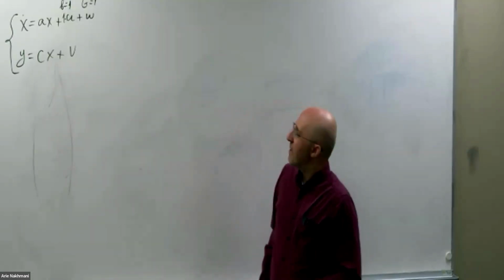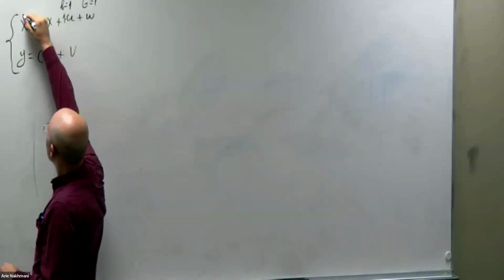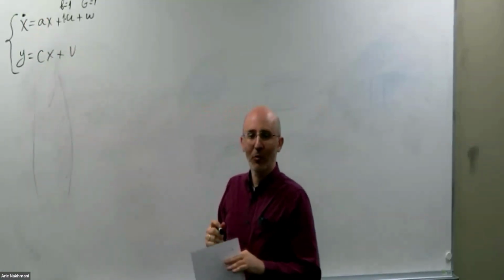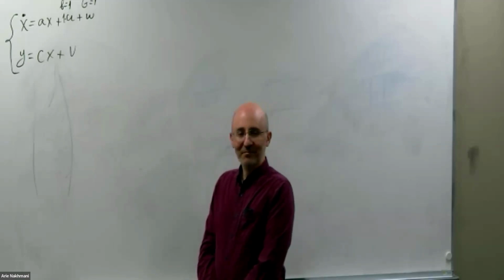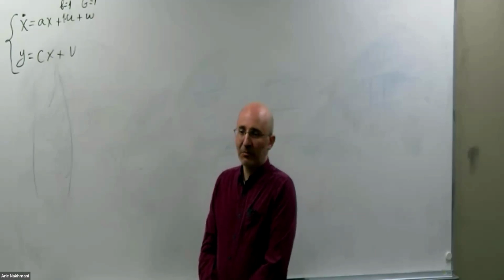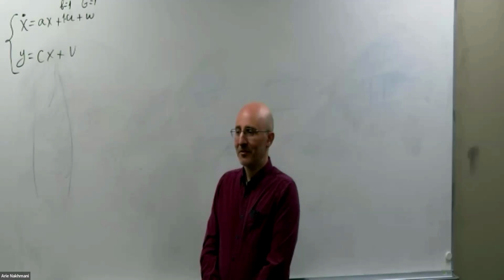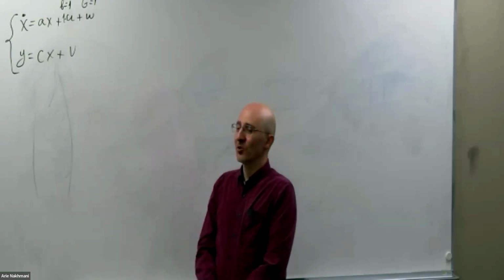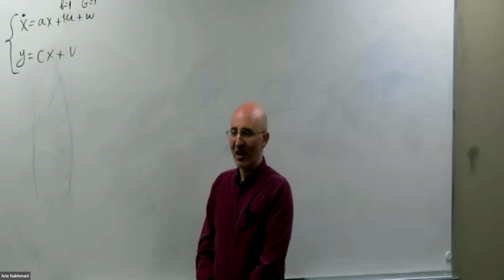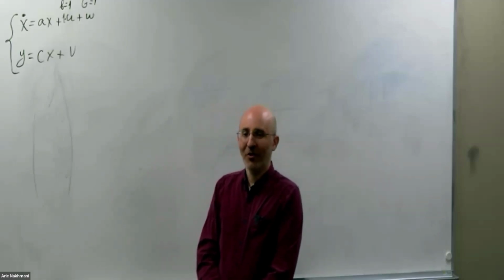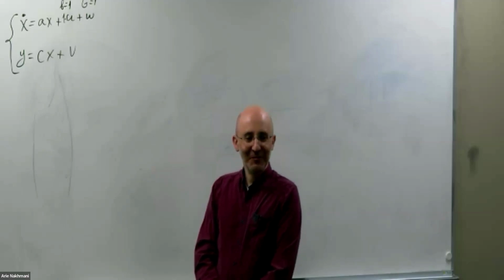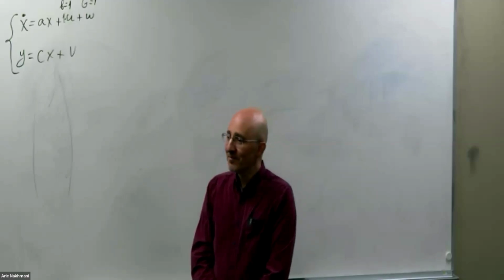They could be positive, negative. What do you think about stability of that system? Will the system be stable in open loop? What is the condition for that thing to be stable? This is a continuous time system, obviously, so all of the eigenvalues need to be in the left semiplane. How many eigenvalues do you have here? Only one. So what is the condition on that one? A needs to be negative for that to be stable.